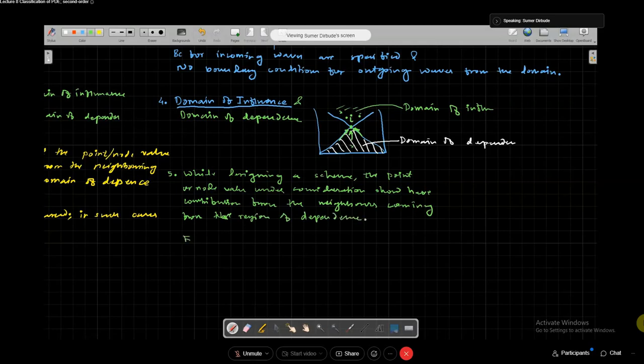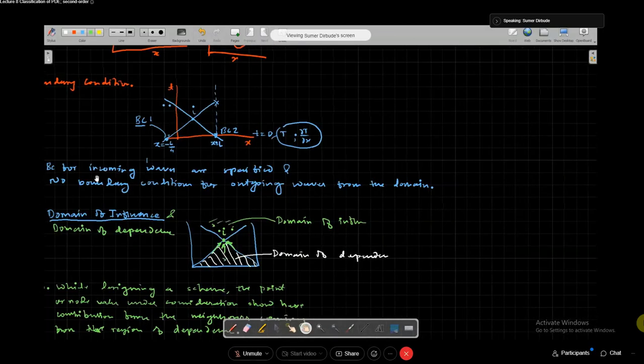Okay. Also, this can be forward in time, or you say marching in time, in a forward direction. So a marching in time scheme should be there. And again, if these situations are there, you may face a problem of stability. So for both parabolic and hyperbolic problems, stability is a major concern. And again, in the hyperbolic case, boundary conditions are very complex. They create a lot of issues, because we always have to see which is the incoming wave and which one is the outgoing wave.